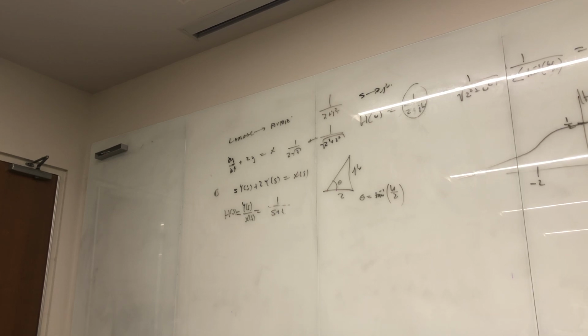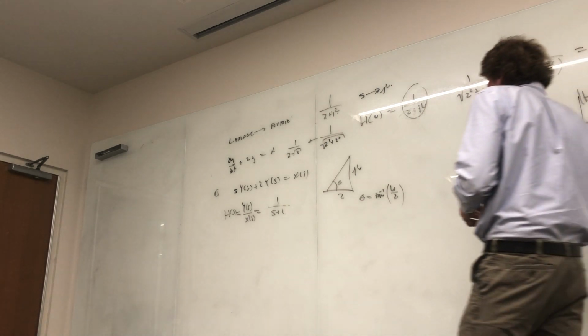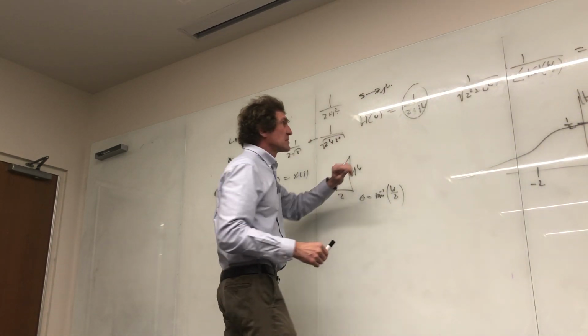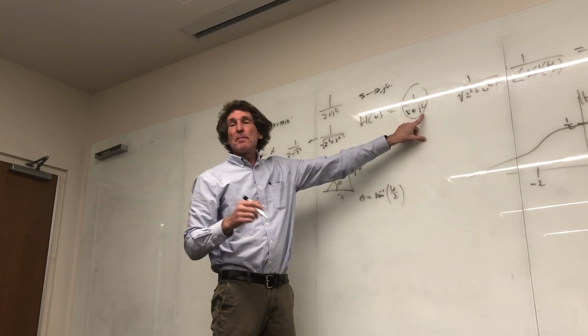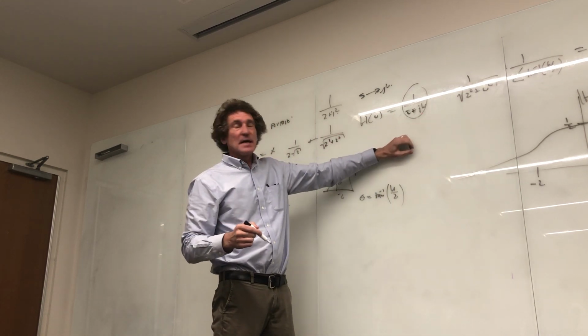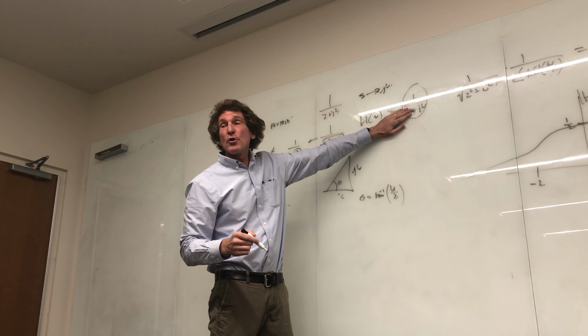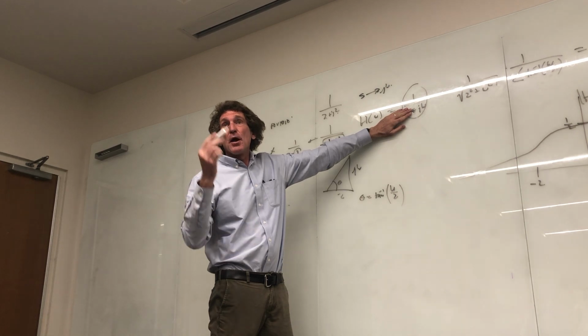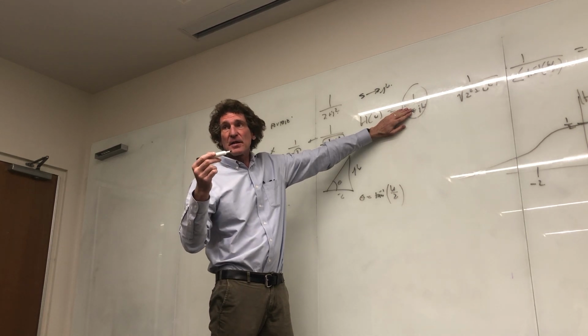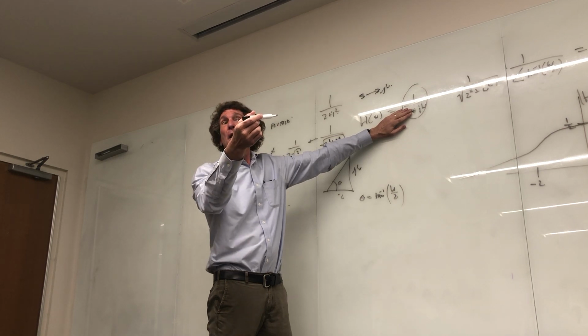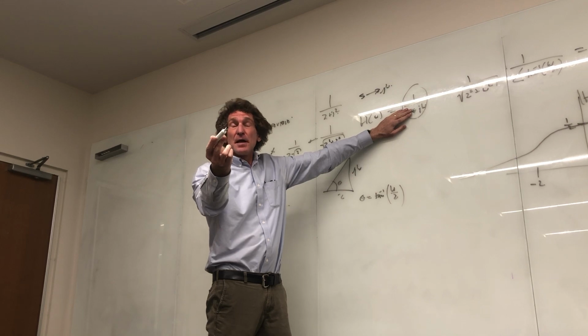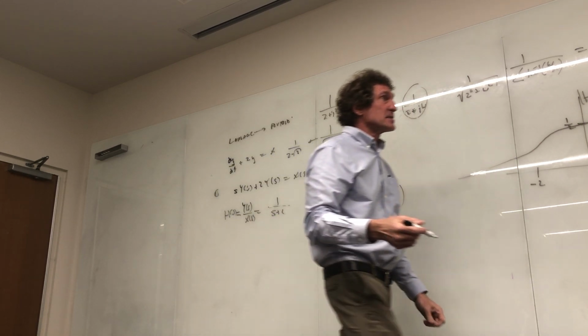What does it do in the opposite direction when I take a look at this function, 2 plus j omega, and I let omega go to minus infinity, right? As it's going there, isn't it about like 1 over minus j omega, correct, class? As omega goes to minus infinity, what's 1 over minus j? Plus j. What is the phase of j? 90 degrees. Plus 90 degrees. It's doing the exact opposite.